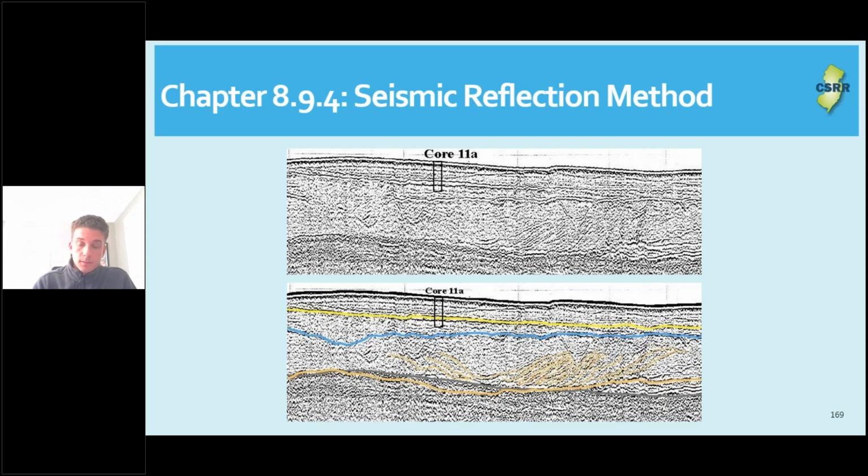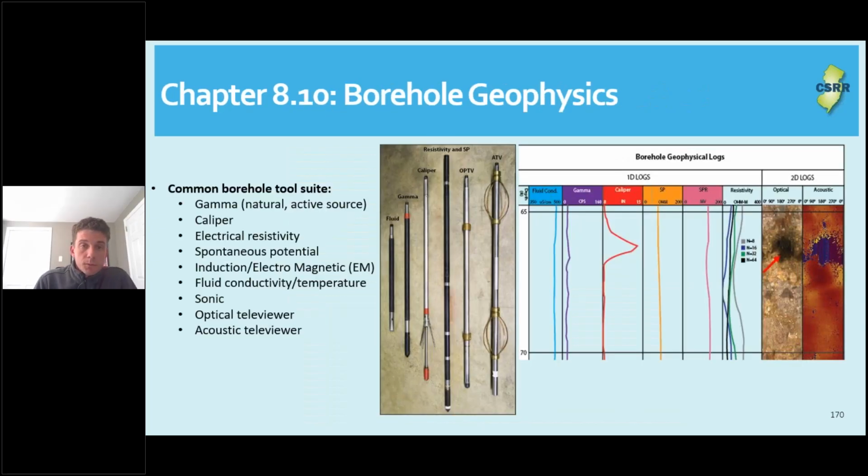So next slide, please. All right, so finally, borehole geophysics. Everything I've shown so far is non-intrusive, for the most part, other than sticking an electrode in the ground. For borehole geophysics, we need a well. But nonetheless, it basically involves lowering and raising a geophysical sonde into a well, which then measures certain properties of either the borehole fluid or the borehole formation. So some common borehole tools are shown here to the right and listed here.